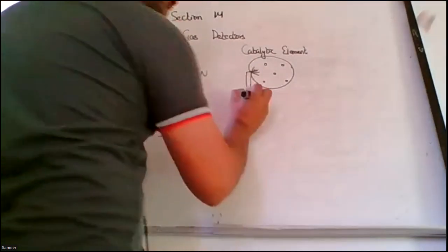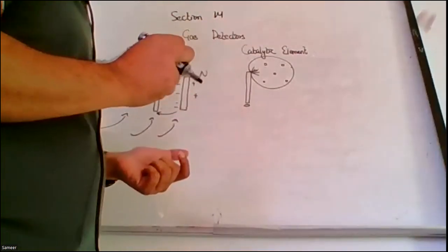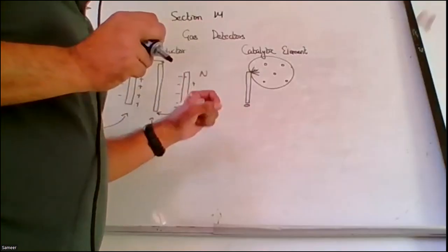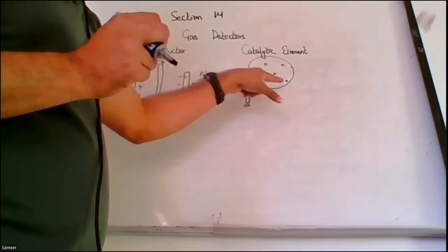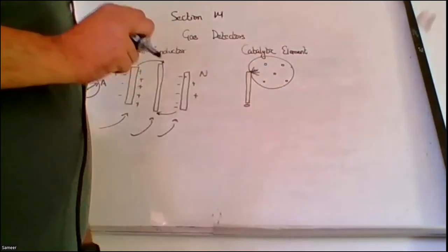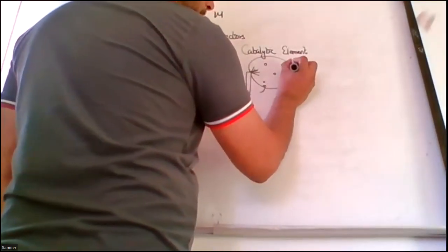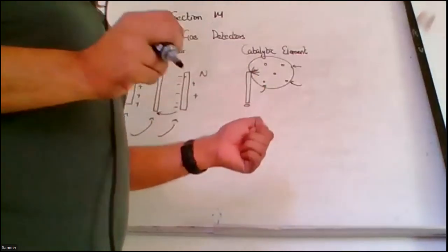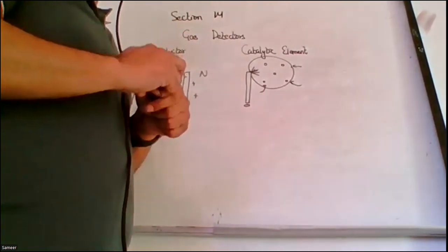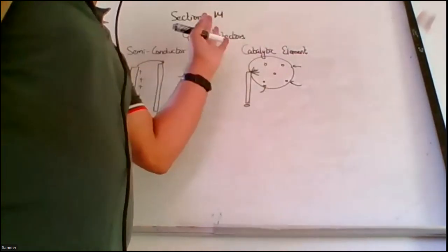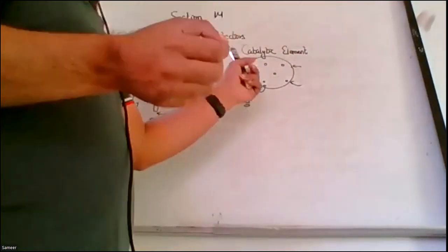There is a button available at the bottom. Usually we used to press the button and a spark will be generated, but nowadays automatic is also there. As soon as the button is pressed, before the generation of the spark, all these orifices will close. Now what happens if any flammable gas enters into the chamber? I press the spark button, the orifice closes, the spark is generated. What will happen to the spark if a flammable gas is there? It will convert into a big flame, and then it will disappear because a limited amount of gas only entered, right?